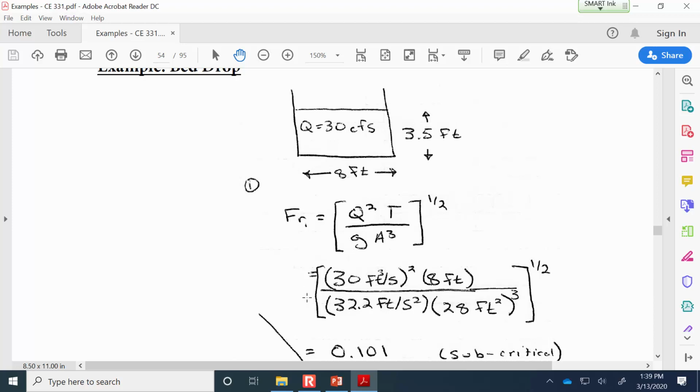Now we have to kind of remember that, because later on, when we do all the substitutions into the specific energy equation, we'll have 3 roots. So I'm not going to show you all the solution yet. I want you to try and set up and solve those 3 roots to find out what are the possible depths that would make the energy balance out the way it needs to. But the clue of which depth to choose comes from this Froude equation where the conditions are subcritical initially.